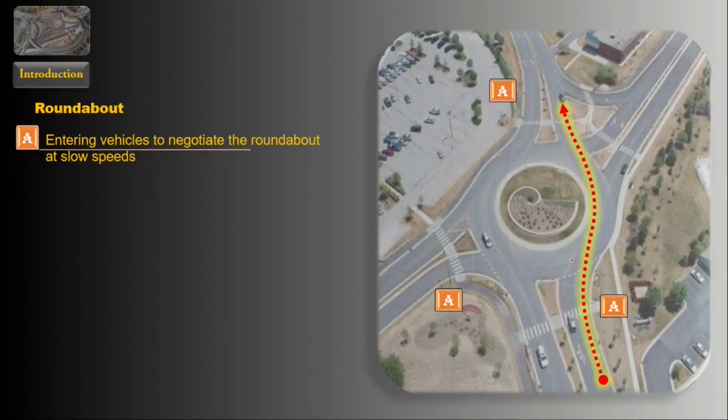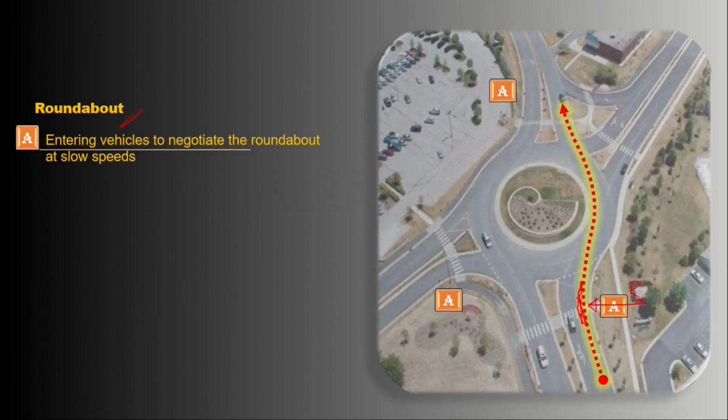But here we're just going to talk about its effect on the performance of roundabouts, which becomes a feature of it. If a circular intersection is to be characterized as a roundabout, this deflection has to be sharp enough to induce a speed which meets the criteria for modern roundabouts, normally less than 15 to 30 miles per hour, depending on the category of roundabout.